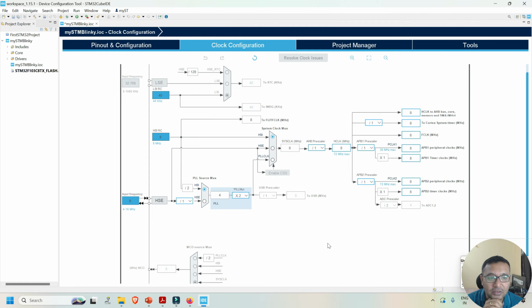So most microcontrollers have an internal clock multiplier. It simply takes the clock externally and then multiplies it internally to achieve a higher clock rate. Now we need to select one of these two options, which clock you are using. Right now in the configuration we have selected the high speed external clock. So just use this over here as a source to this PLL.